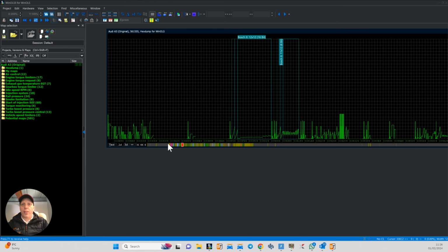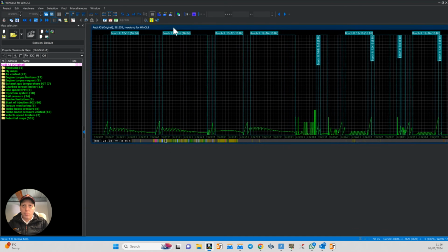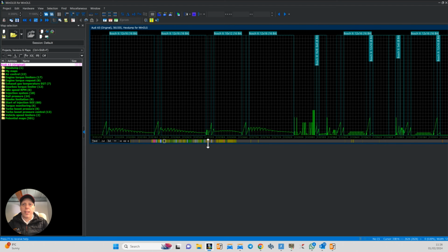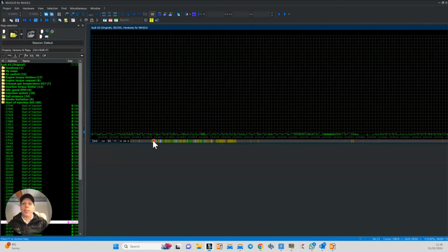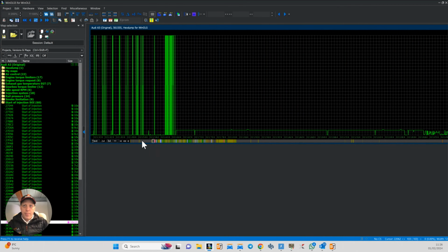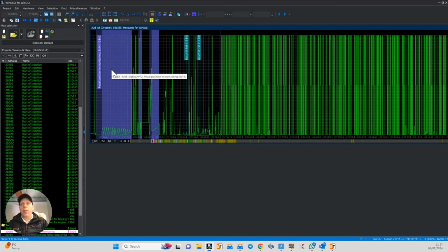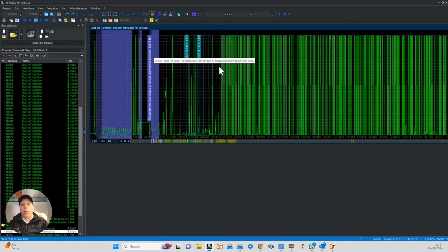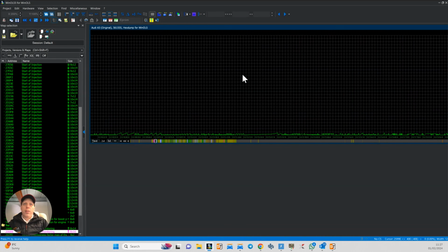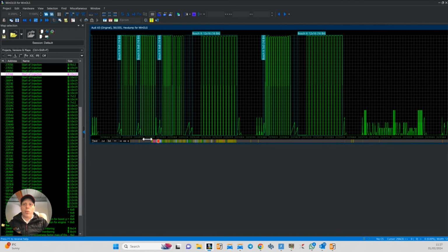Now, if we have a flick through on WinOLS, so when you're looking at WinOLS, anything in this coloured area here, WinOLS has picked out as a calibration area, so it's part of where the maps are going to be. So now we can see things are in blue. If you hover over them, we can see what they are. So we've got pedal position and monitoring. We've got part of the torque monitoring. And then if you flick through, we've got soy maps.